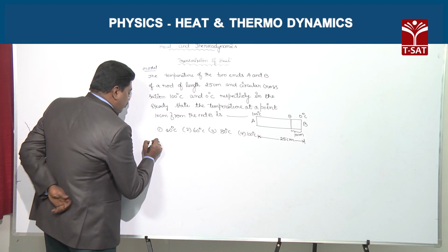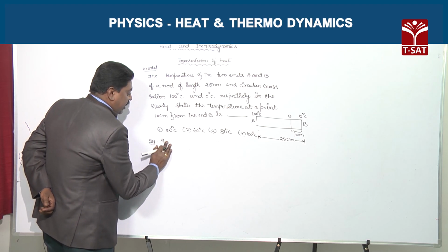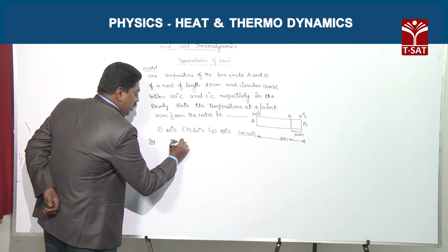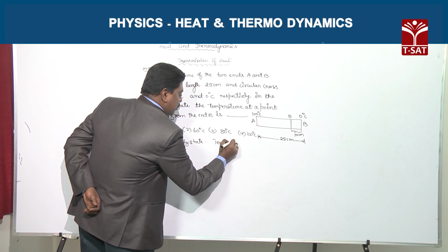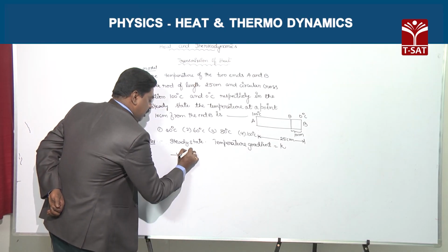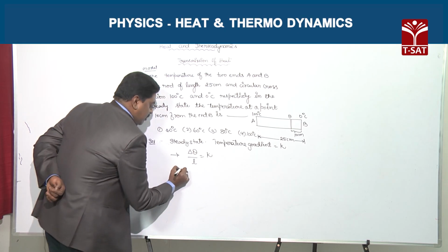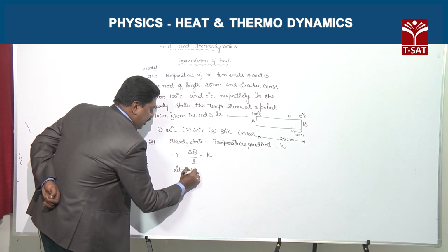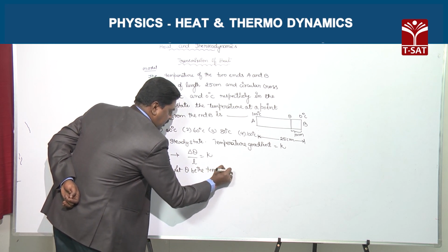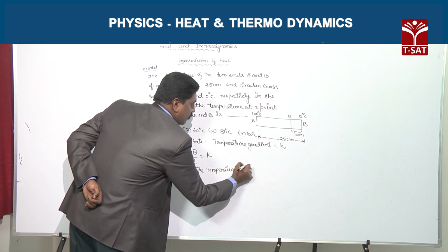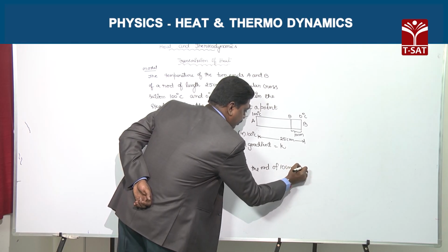Okay. In steady state, a word is mentioned in the problem, said as what? Steady state. Okay. In steady state, temperature gradient remains constant, implies delta theta by L equals K. Let theta be the temperature at the end of 10 centimeters from B.